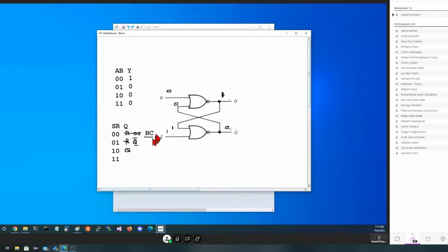We then have the last case, which is turning them both on, and we already know that if we try to set both of them, meaning this is a 1 and that's a 1, there's no way for us to get a 0 over here. Because to get a 1, we have to have the case where we have 2 zeros in the input. There's no way to get a 1 over there. We have to have 2 zeros. So this, again, is going to be a disallowed state.